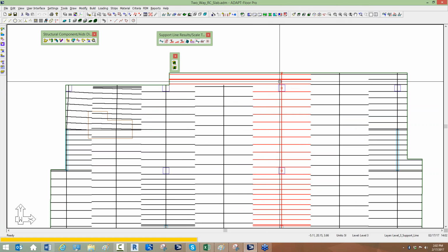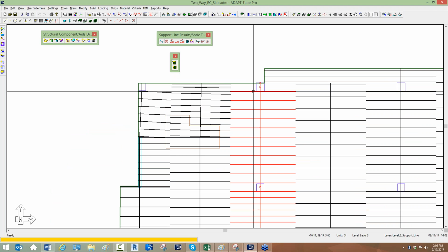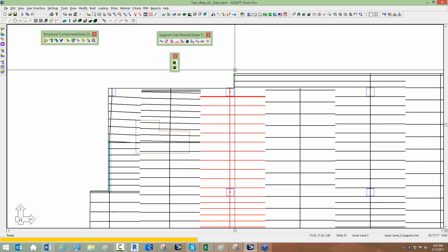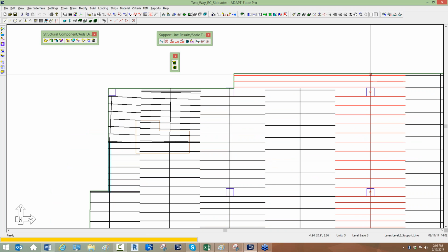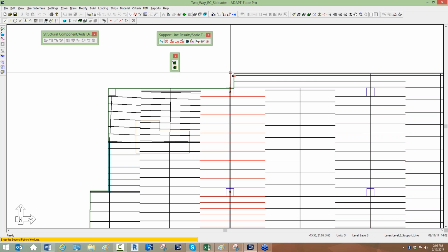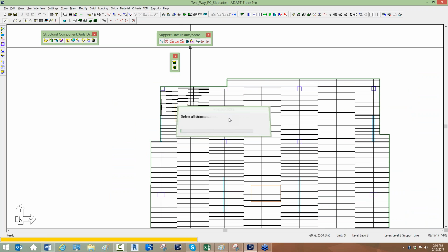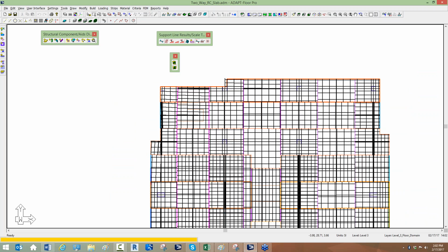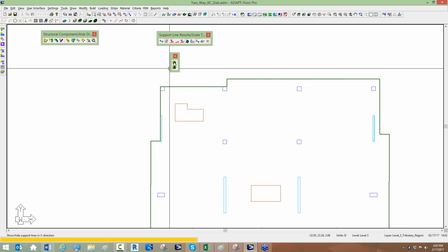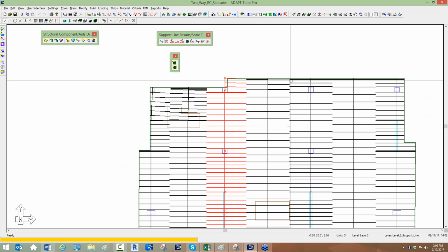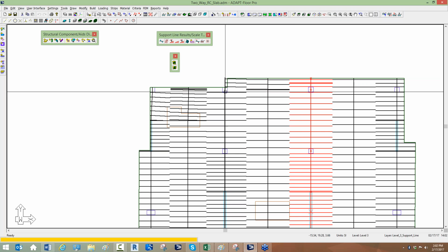By the way, this is cutting all the way over because this strip right here terminates at the slab. It's actually short because of this corner that turns up vertically. This one extends up, this one does not. If I was to move this out of the slab, like so, and regenerate my strips, I would now get that broken out how you might want that. So this now looks something like this. This now extends over. This doesn't cut all the way over to that edge because I've now extended the other column strip vertically to be aligned approximately with this one here.